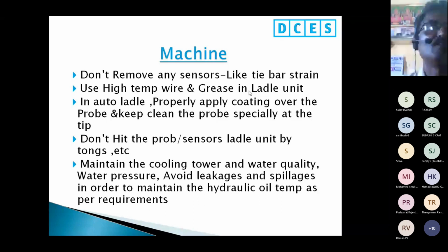In the auto ladle, properly apply coating over the probe and keep the probe clean, especially at the tip of the probe. Operators need to be trained properly. Otherwise, they apply the ladle coat at the tip of the probe, and it doesn't sense properly. The auto ladle will dip into the material. This is a very, very dangerous problem happening in die casting. So the tip should be kept clean. They should be educated properly.